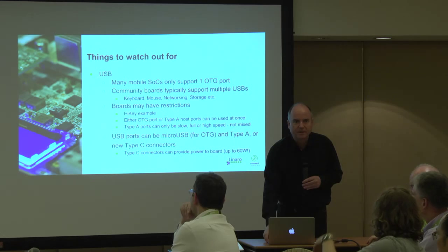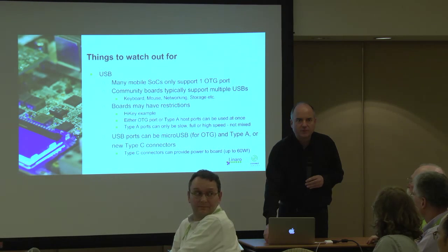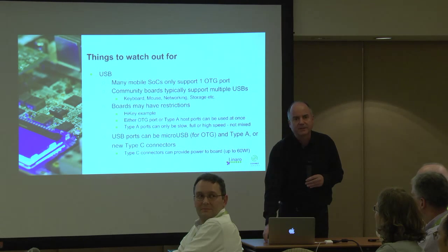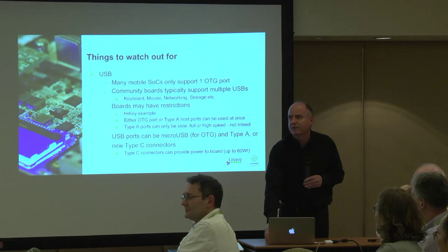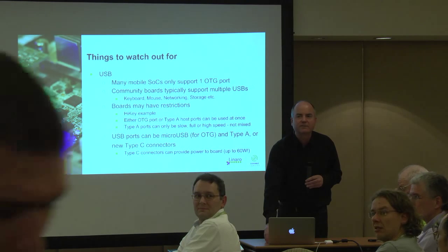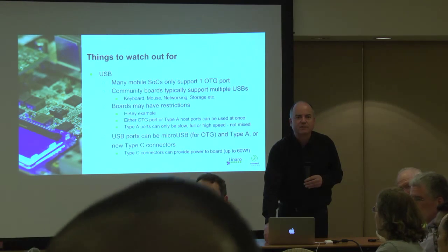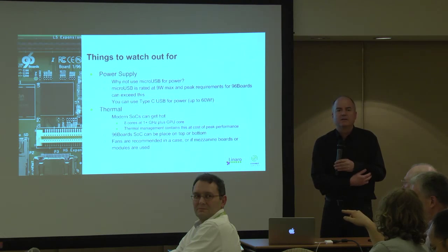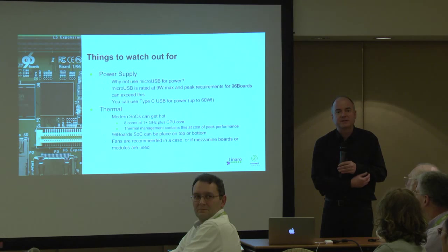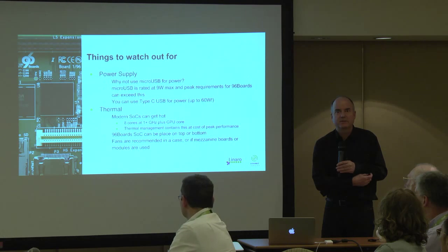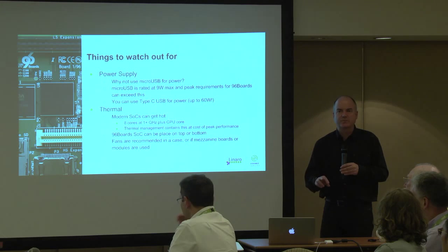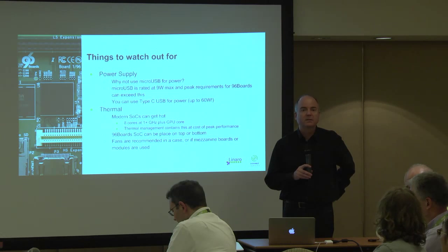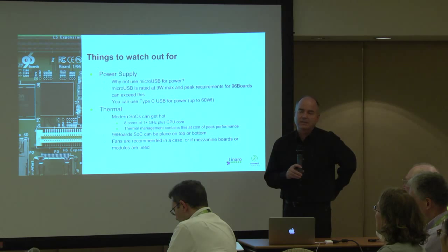Is the SoC always SuperSpeed, or can it be? Type C is SuperSpeed. No, it doesn't have to be. It's a PHY, so you can put lower speeds on it, as far as I remember. Have we got any USB Type C experts here? Where's Leif? No, you'll need to read the spec. I was wondering what 96Boards says. 96Boards says you can use a Type C connector, and the assumption, as far as I remember, is that with a Type C connector, it's the USB 3.1 spec, and you can run any speed on it that you want. So you can use an SoC that only has high speed? Yes, that's my understanding.